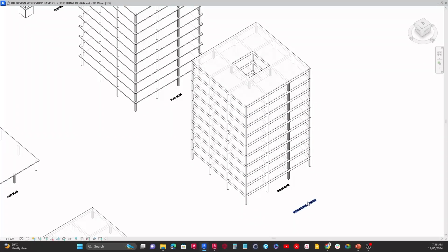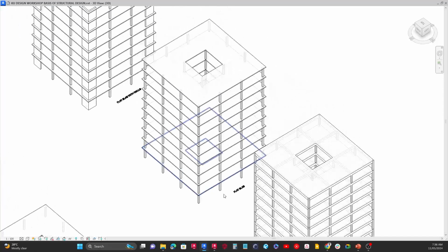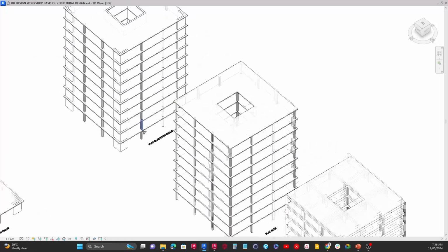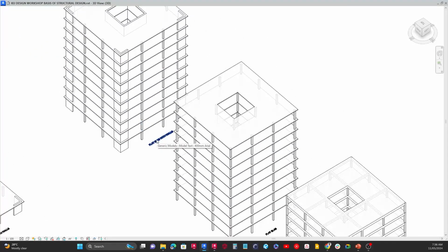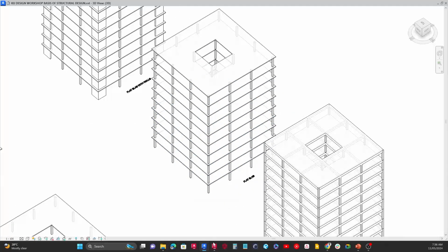So we have this structural system, but with stacked stories. We have different stories over here. We can see that this one is the solid slab system, this is the flat slab, and this one is the flat slab with walls. Let's look at how all of these affect our analysis. The first thing you want to look at when analyzing larger structures like this is the displacement, the displacement affecting the slab, because ultimately that is going to determine the thickness of your slabs.